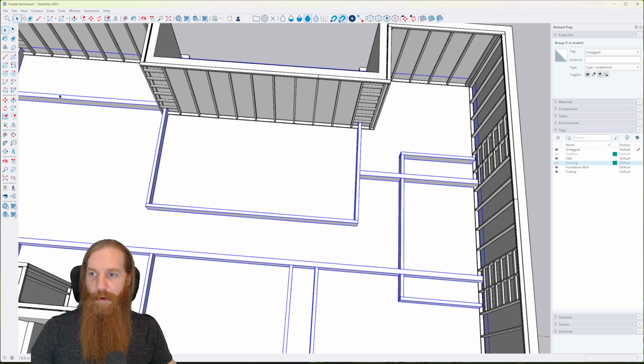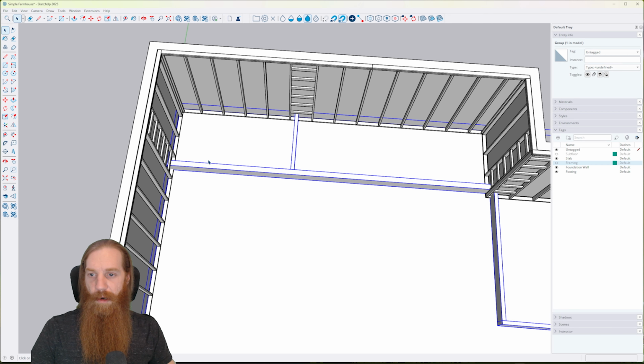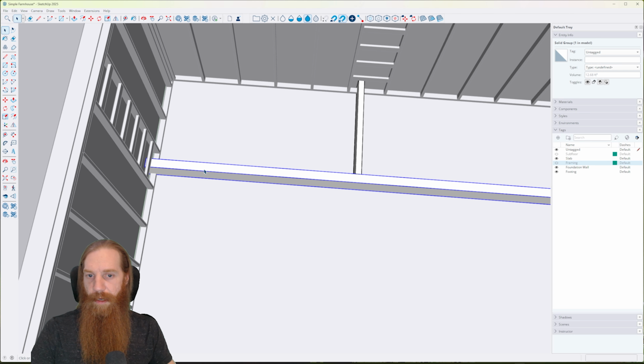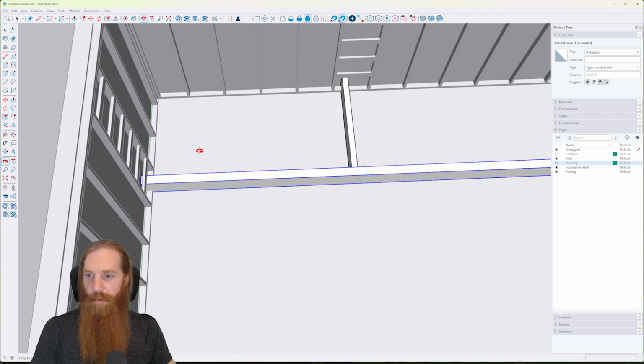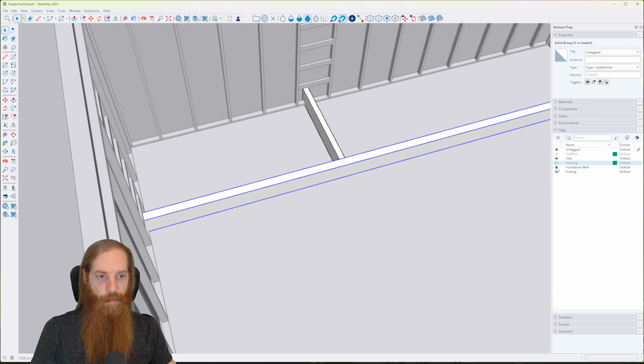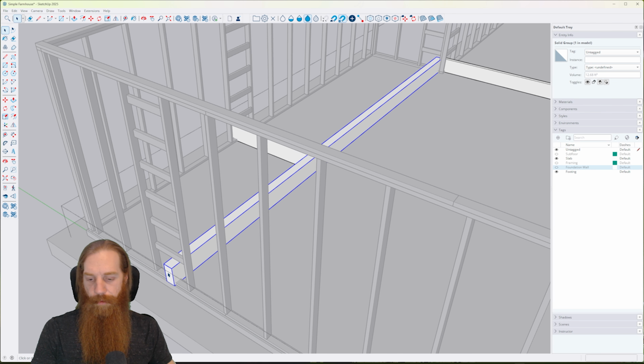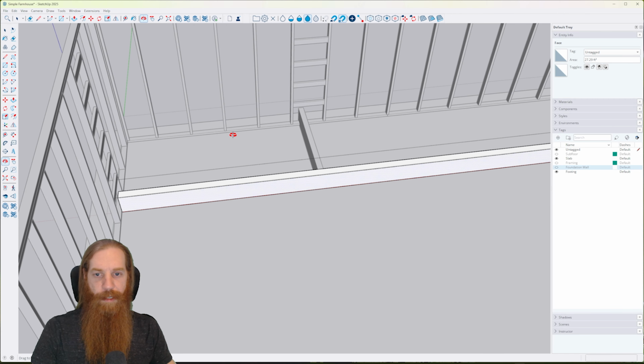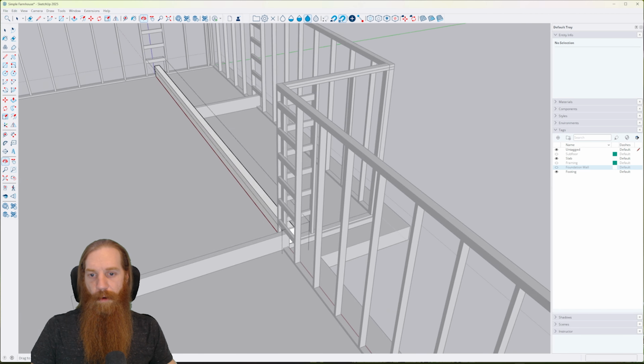I think what we're going to do, we're going to build all of our top plates on top of these temporary walls, these little wall markers. I'll build the top plates on top, then we'll delete these out, and I'll move all the bottom plates down to the floor level. So let's start right over here. And then I also would like to, I guess I could remove each one as I go, but probably won't do that. Let me take the foundation wall off real quick, because I want to resize this one to match where our wall will actually be.